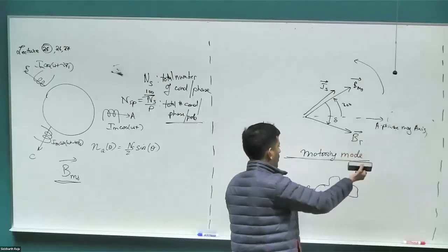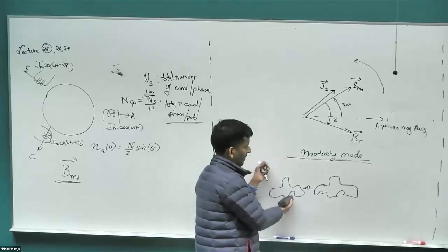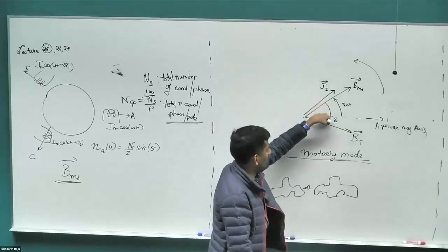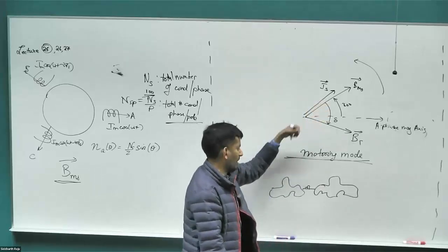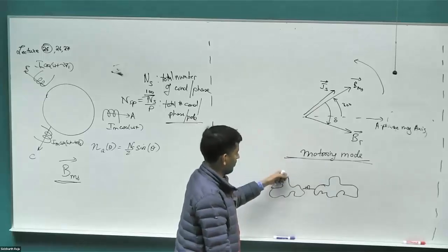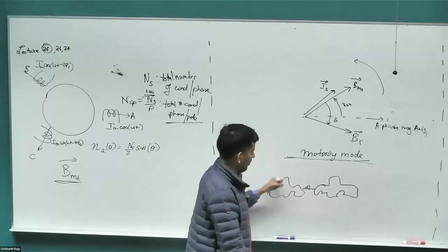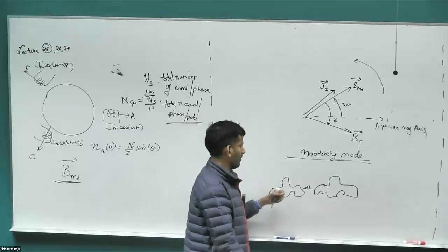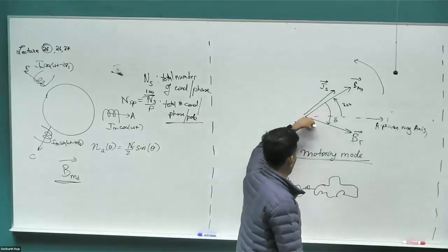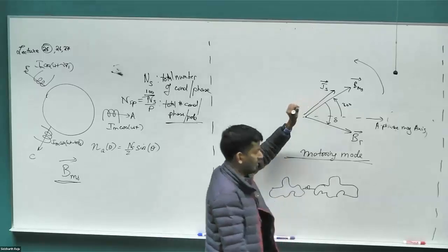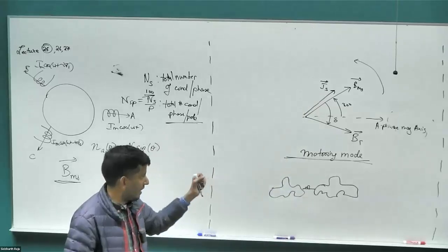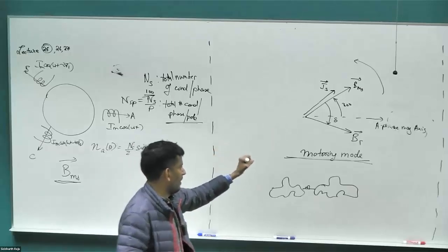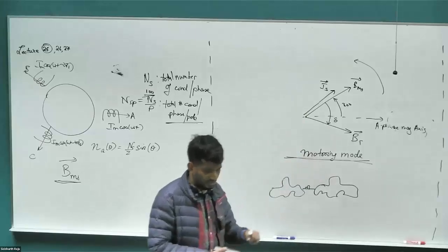So whenever you apply more load, think of swapping the car that you're towing to some other heavy load. The spring that's connecting these two cars is going to stretch out. And that's basically the delta angle increasing between the two. And it can oscillate back and forth. Let's say some sudden boulder falls on this and you're still having the power to pull it through. It'll go back and forth, there'll be some oscillations going on. But at steady state, they would have to stay together, right? So this can swing around and settle in a new angle, but they're all rotating at the same speed at steady state whenever we draw a steady state diagram. In the textbook, we only consider steady state. In the class, we have considered the transient case as well. But whenever you see the textbook diagram, it's completely steady state. So all of these space vectors are rotating at the same speed.